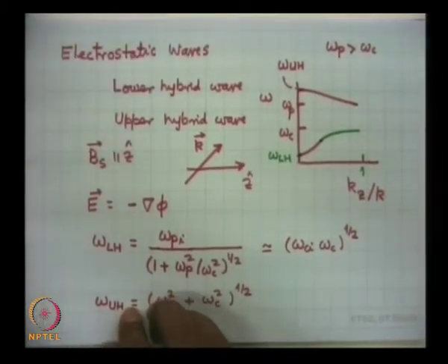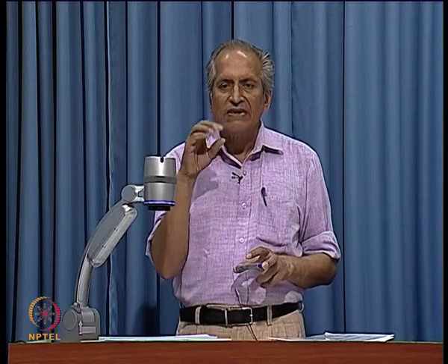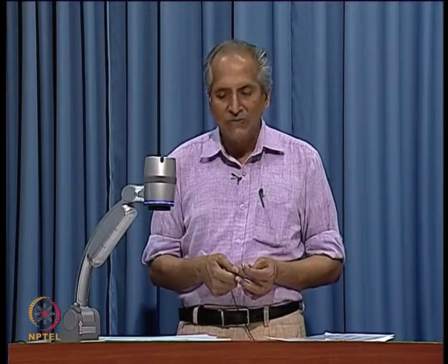We already got a clue that a beam moving with such a velocity that the frequency of the wave as seen by the particle is nearly 0, then we say that the particle is in phase synchronism with the wave and it can very effectively exchange energy with the wave. So, the main requirement has been to find a frequency such that some moving particles in the system, either electrons or ions, see the wave to be some sort of electrostatic wave, or the effective frequency is 0.